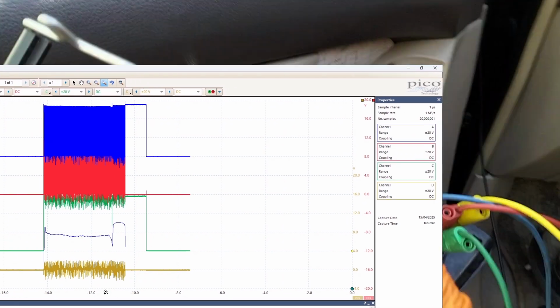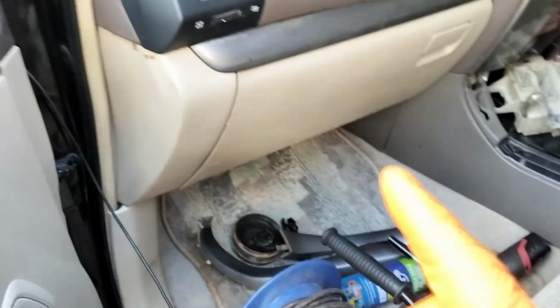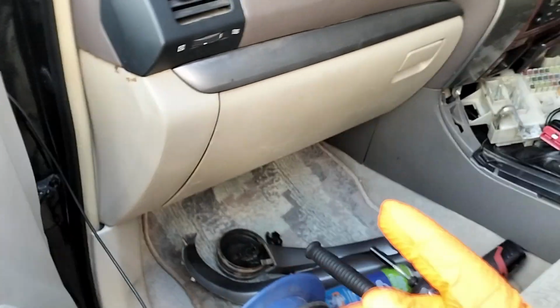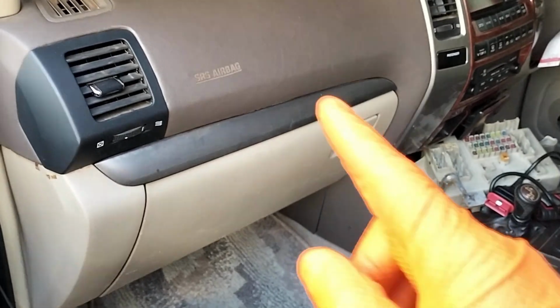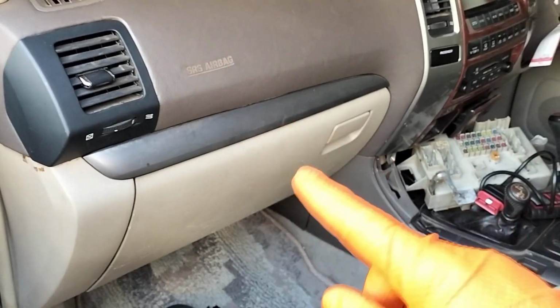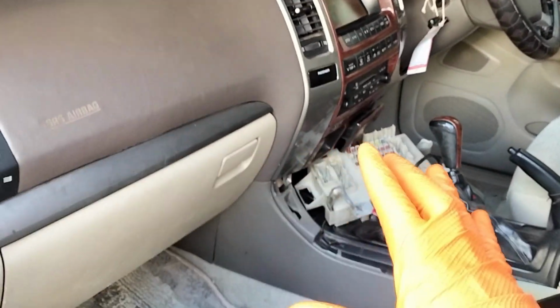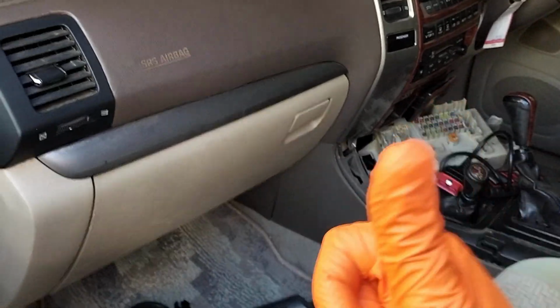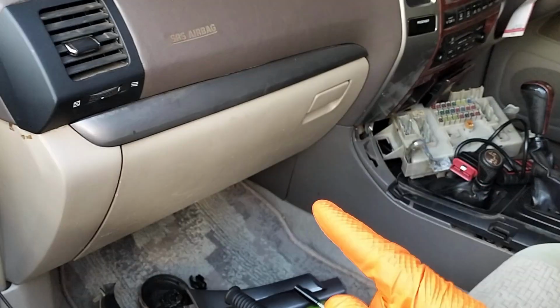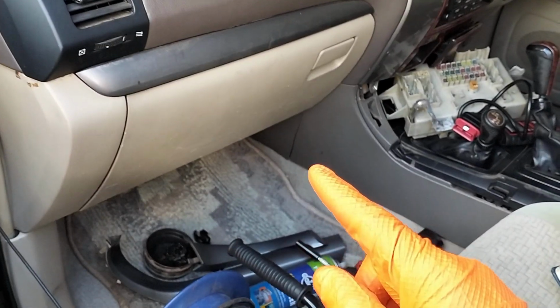So this is good. Now I know why this is not working. Since the speed sensors back here are not working, what it simply means is the automatic function, which is what the driver switch gives, is completely disabled. So this rear window needs a new motor.